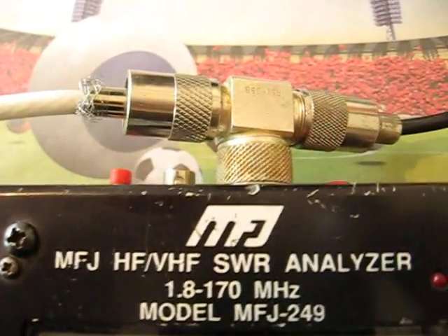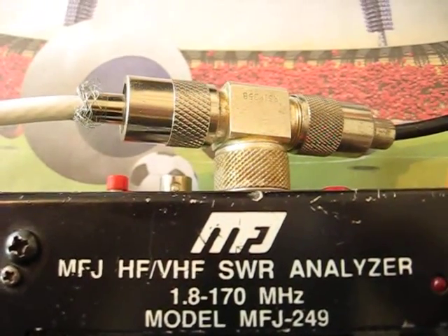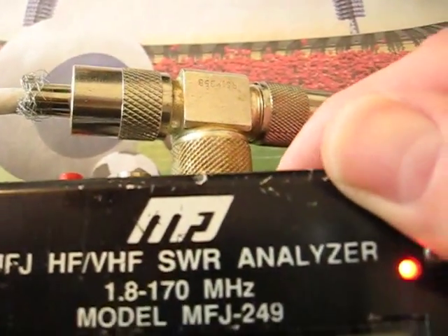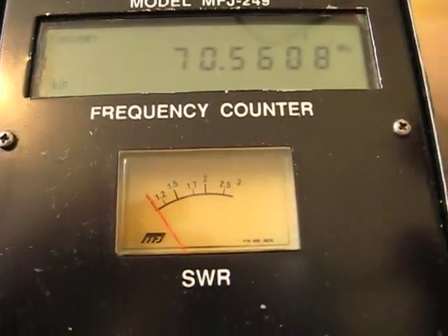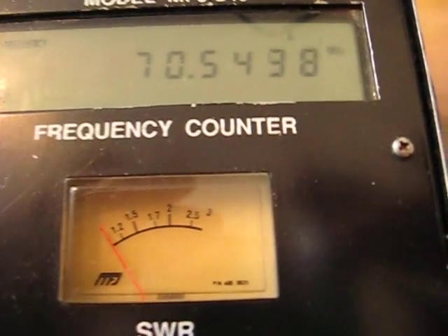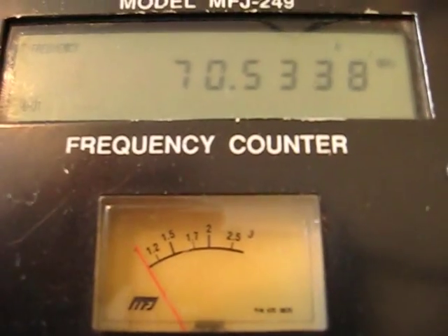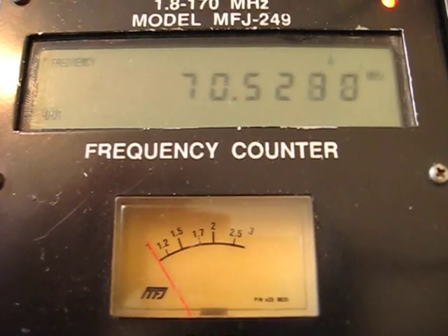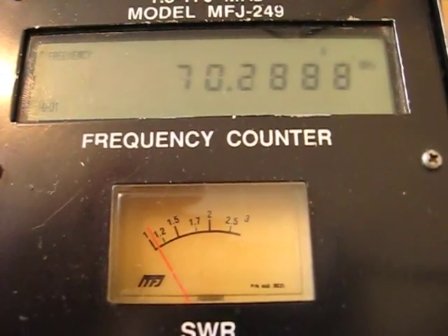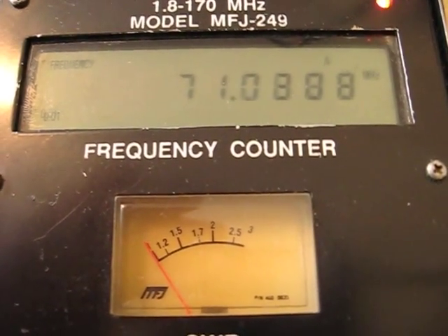And when I heard about this idea, I quickly put the 75 ohm on and was assured that it was on the frequency I wanted. Half wave, multiples of. So there it is. It's on 4 meters, 70 megs. As you see, coming to the dip, which is just there, about 71 megs.